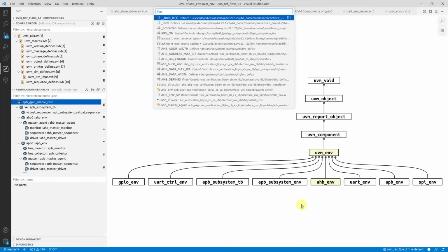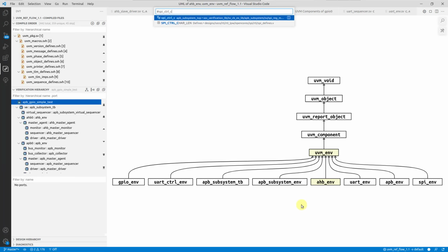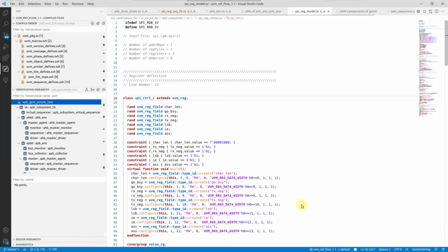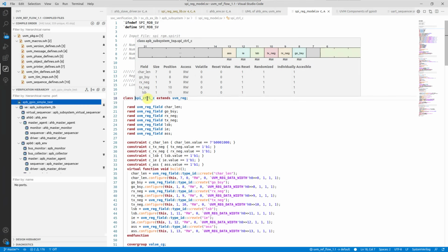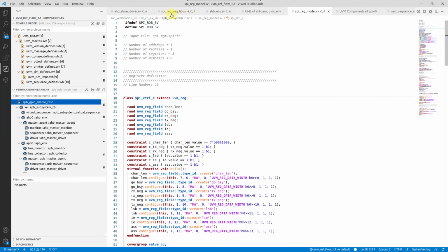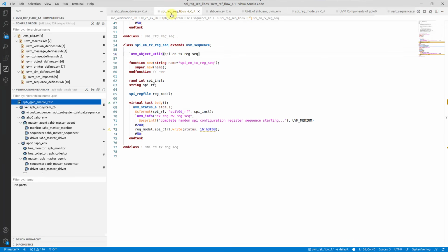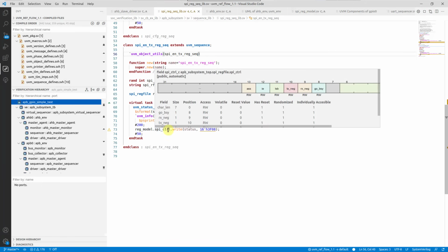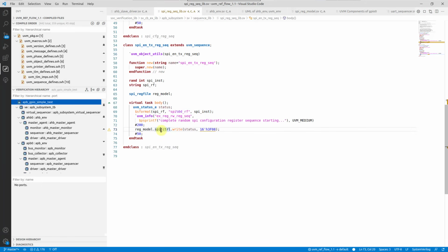Let's look at another type of diagram which highlights the benefits of choosing an IDE instead of a plain text editor. Simply hover a register class name to see a bit-field diagram in the tooltip. It visually represents the bit fields alongside a configuration summary table. Even handier, you can get the same for a register instance in a different file, perhaps where it's referenced inside a sequence. This time, let's trigger the Show Diagram command to see it in a separate editor.